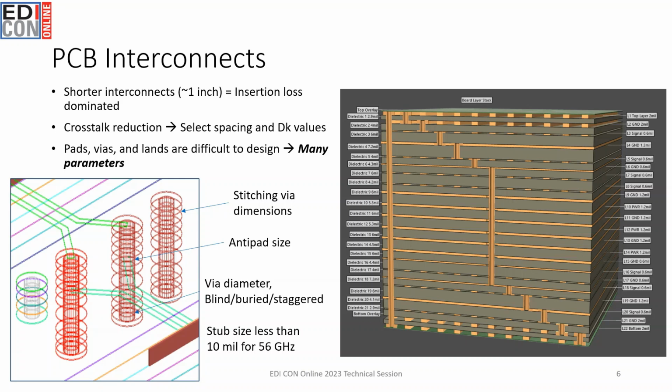It's because, of course, there are so many parameters, but also we need to get some sort of sense of how changing one of these parameters affects the loss in these interconnects. And that's not so intuitive. In some ways it's intuitive at some frequencies, but then there can be a switch to non-intuitive behavior at other frequencies, and changes in these parameters that are required to achieve impedance matching and minimal loss and reduce crosstalk are all interrelated with each other.